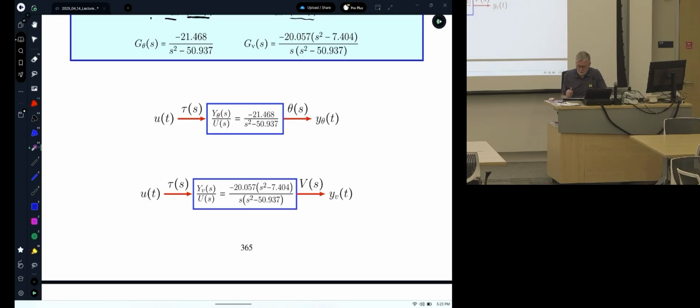What we're going to take advantage of is that this transfer function can be written as this one times this numerator term, this denominator term, and then, what does it take to go from 21 to 20? You multiply by 0.95? Okay, so that's the constant. So this transfer function is essentially 0.95 times s squared over that, divided by s times this one. And so you can think about it as being here, and we're going to take advantage of that structure.